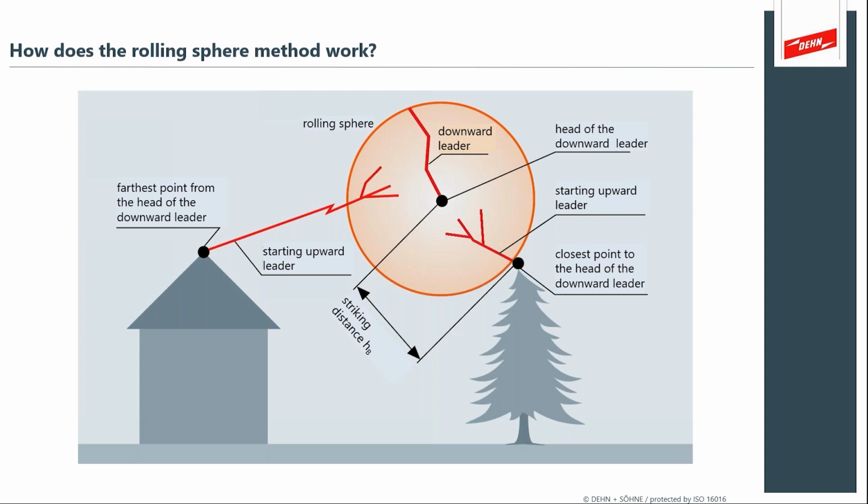And so what we could see is that if you understand that the last final step leader is essentially trying to provoke an attachment in all of three-dimensional space, you can use that as a calculating method to discover where lightning would prefer to attach.